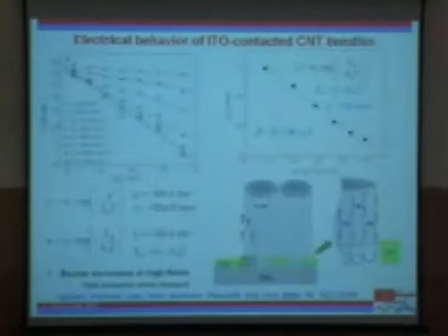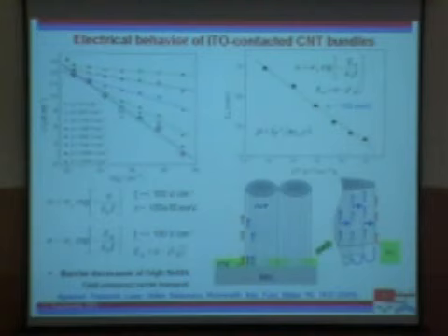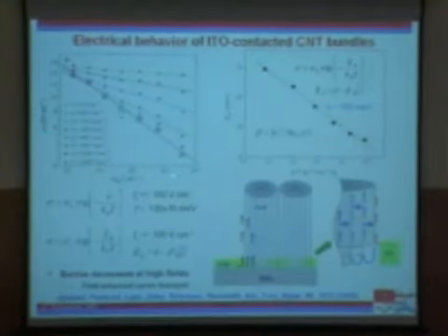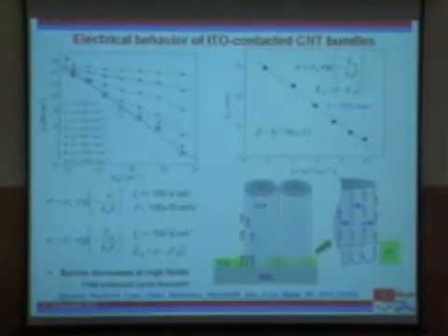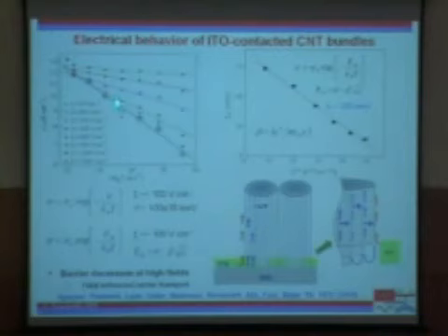The reason for this we have figured out by a variety of different experiments and also density functional theory calculations: the conductivity in this particular case is thermally activated, and that is not surprising. These carbon nanotubes are semi-metallic, and the interesting thing is, when you increase the electric field across the terminals, the activation energy actually decreases. So that's shown over here.